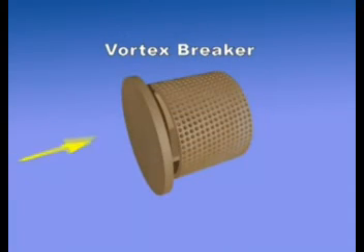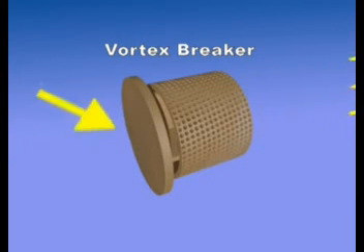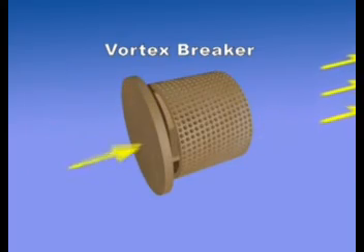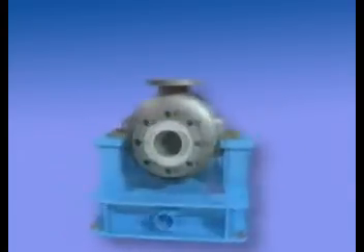Vortex breakers are devices that can be found at the liquid outlets. They are designed to eliminate gas carry under in the liquid stream. The vortex breaker will stop the swirling of the liquid. A vortex-shaped swirl has the tendency to suck vapor into the liquid stream that could cause pumping problems.